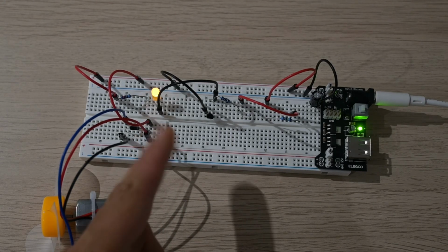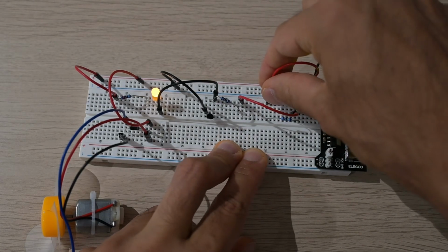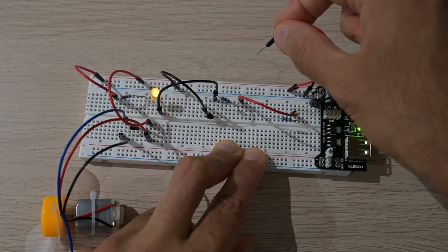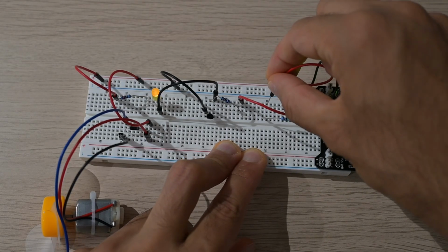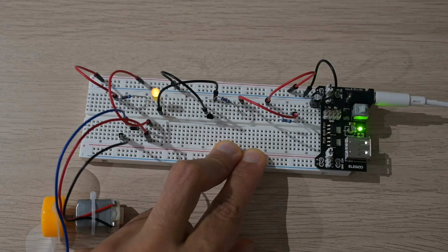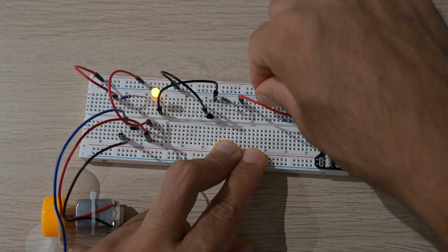In this case, a BJT has its base connected to the RC circuit, and upon its activation, a LED and DC motor are activated. Also notice that here I've learned my lesson, and here I'm using a flyback diode there on the left to protect the circuit against EMF voltage spikes.